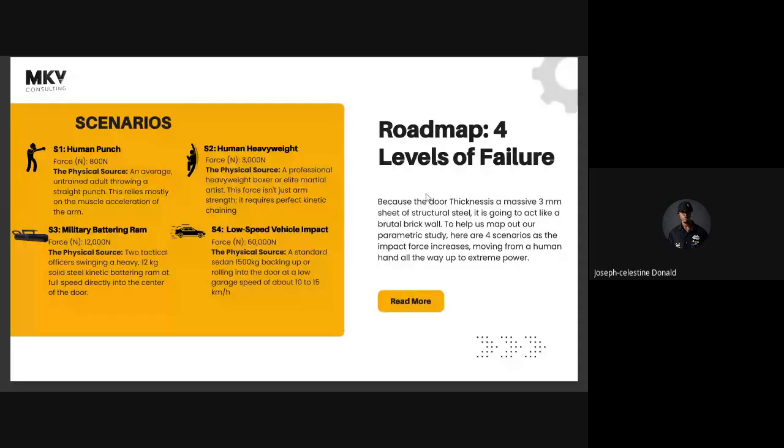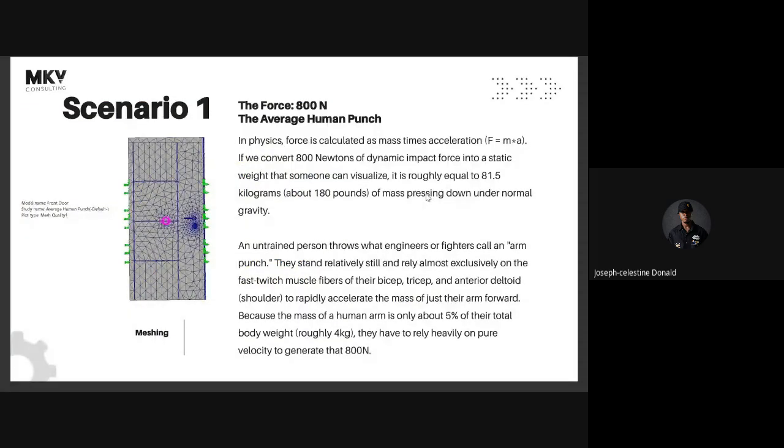Now, what you should understand is we've selected the material for this, and we've picked the geometry, the size. When it comes to geometry, one thing we didn't talk about is the space where the force is going to be applied. Of course, if you punch a door, the impact cannot be on the entire space of the door. So what we do is we pick a specific point on that door itself. You can use cut, but cut is going to create a hole, a gap in that section. So you use your split line instead.